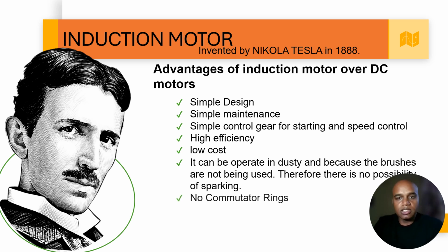This makes it a very versatile motor, because in industry we have dust and we have oil contamination. Both dust and oil contamination are very hazardous for DC motors, because they can produce sparking and further require maintenance, whereas the induction motor can withstand very dusty and oil-contaminated environments. Therefore industry likes it, and it has been called the robust motor for industry applications.